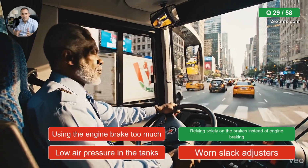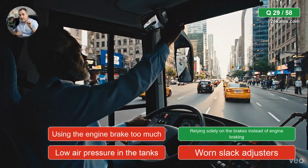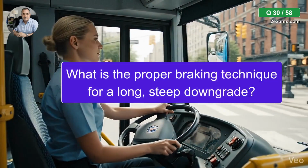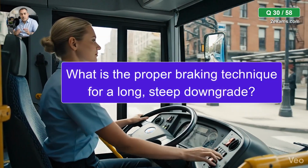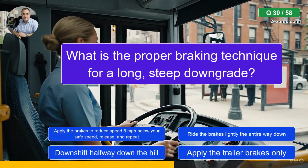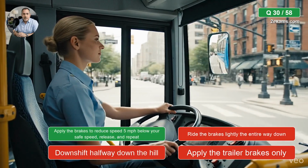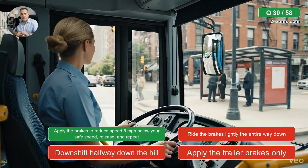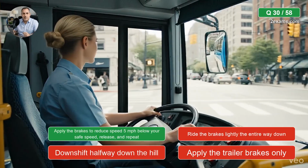The correct answer is, relying solely on the brakes instead of engine braking. What is the proper braking technique for a long, steep downgrade? The correct answer is, apply the brakes to reduce speed 5 miles per hour below your safe speed, release, and repeat.